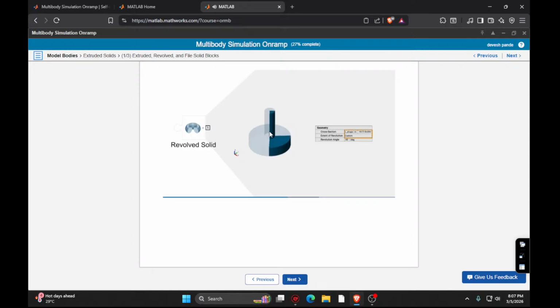That rotation creates a 3D object. In our case, that's a revolved solid. You still start with a 2D profile just like before, but instead of extruding, you spin the shape about the Z-axis. Your spinning can be a whole 360 degrees, creating a full 3D shape, or it can be a partial rotation, sweeping symmetrically around the Z-axis. This will be perfect for making the gears.